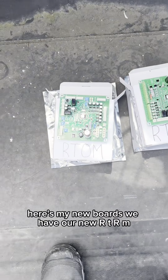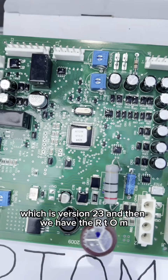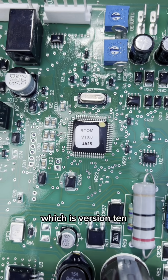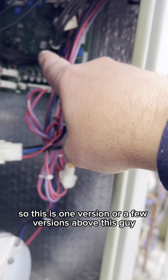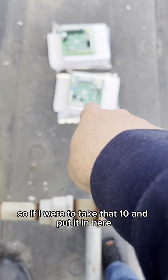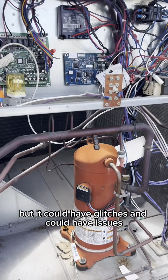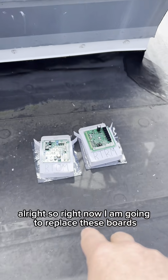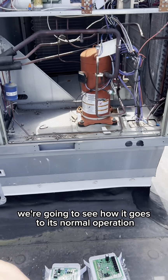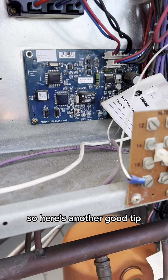Okay, here are my new boards. We have our new RTRM, which is version 23, and then we have the RTOM, which is version 10. So this is one version, or a few versions above this guy. So if I were to take that 10 and put it in here, most likely the unit would come on, but it could have glitches and could have issues. All right, so right now I'm going to replace these boards, and then we're going to see how it goes to its normal operation, and it'll allow the gas heat to function. So here's another good tip.